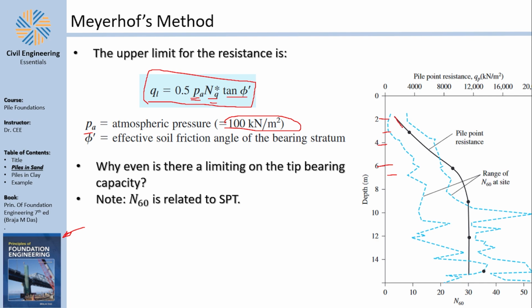And then they plotted their bearing capacity curve with respect to the depth. And you can see that the bearing capacity increases to a limit, to a certain depth, and then just doesn't increase at all. The bearing capacity becomes unaffected by the embedment depth.